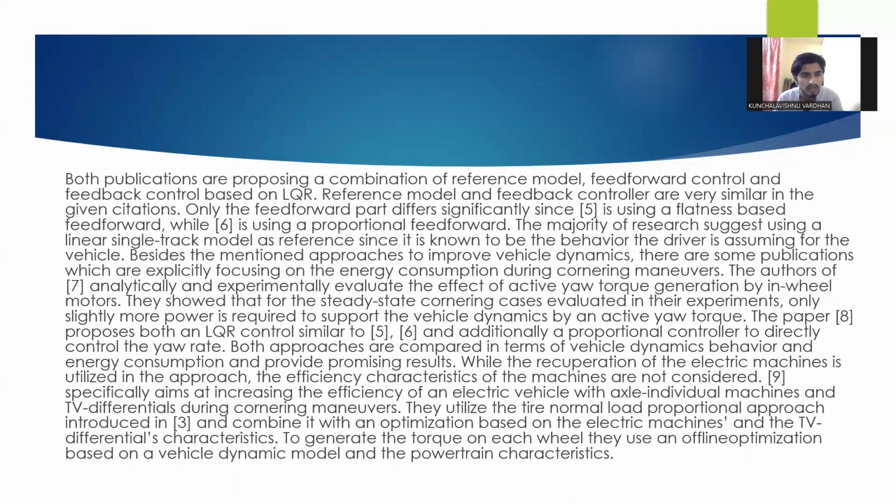The authors analytically and experimentally evaluate the effect of active yaw torque generation by in-vehicle motors. They showed that for the steady-state cornering cases evaluated in their experiment, only slightly more power is required to support the vehicle dynamics by an active yaw torque.